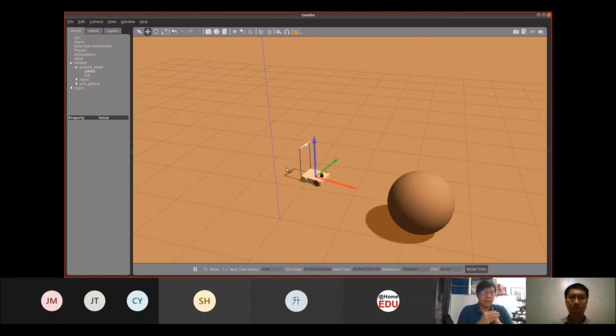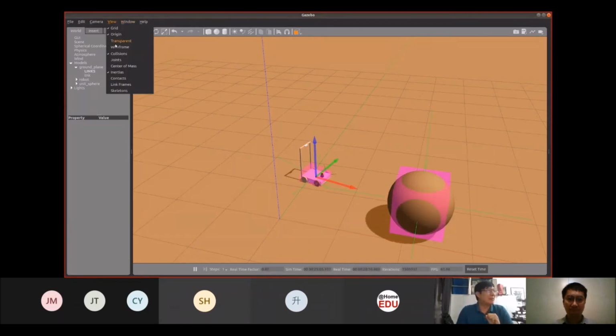But once you play with collision, make sure the mass is correct also. When multiple free-moving objects interact in the simulation, you need to make sure the inertia and the center of mass are correct.